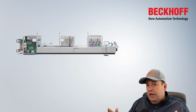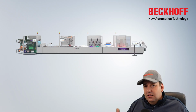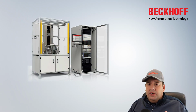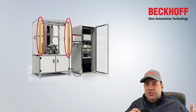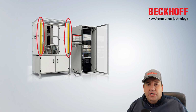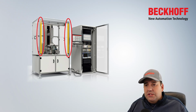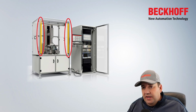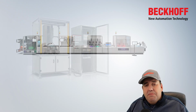possible. If an omitted option is added later, the group and associated hardware are easily activated. Temporary deactivation is only used during commissioning. Examples include temporary deactivation of not yet installed guard doors or light curtains. This allows engineers to continue commissioning or training a machine with missing components. To avoid inadvertently leaving a safety function deactivated, the group is restarted following a power cycle.